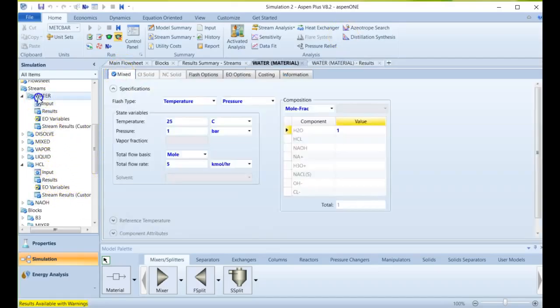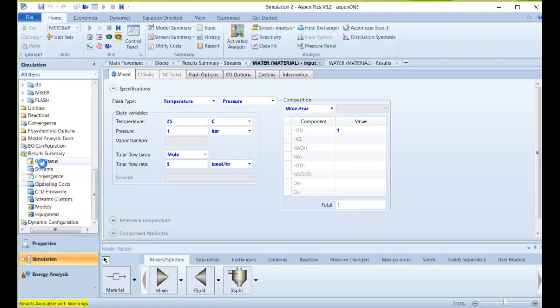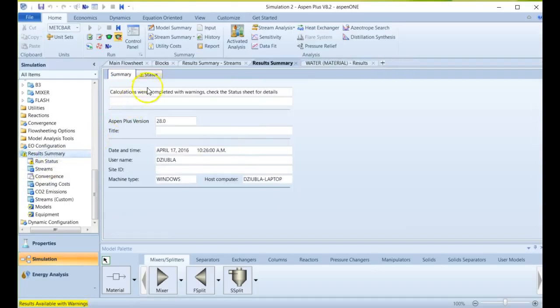But anyways, one of the things to be careful of is if you do see these warnings, to read what they are and check to see if they make sense or if they're valid or not. There are really 3 modes to which Aspen can output data. One without warnings, one normal with warnings, or just crash entirely. Crash entirely, or errors, just won't converge and give you rational results. The warnings, they can be rational depending on what's happening. In this case, this is completely fine, but sometimes the warnings may actually give you errored values as well.